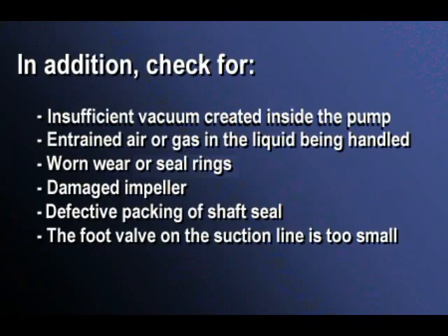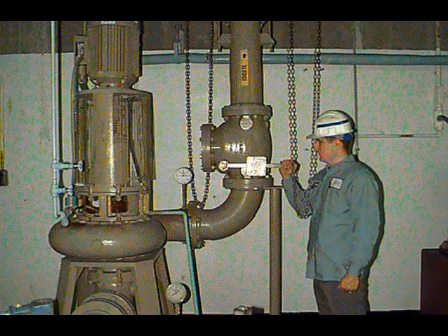The foot valve on the suction line is too small. The check valve is not operating properly. The direction of the impeller rotation is incorrect. The impeller is mounted backwards on the shaft.